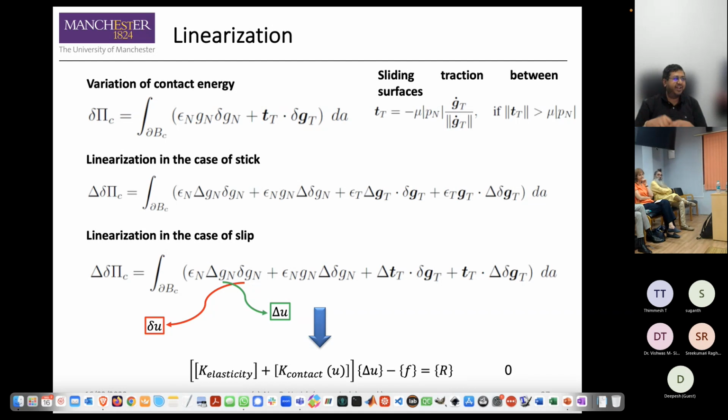People say that most of the cracks would go through the rubber and not through the filler. But we saw that most of the cracks went through the interface, and there were also a few cracks that could go through the filler as well. So we wanted to see how we can capture these things, and it does happen in a way. So we used the cohesive law. Now, what are the properties of this cohesive law? Again, we put in some assumptions there, another set of numbers that are very hard to estimate.